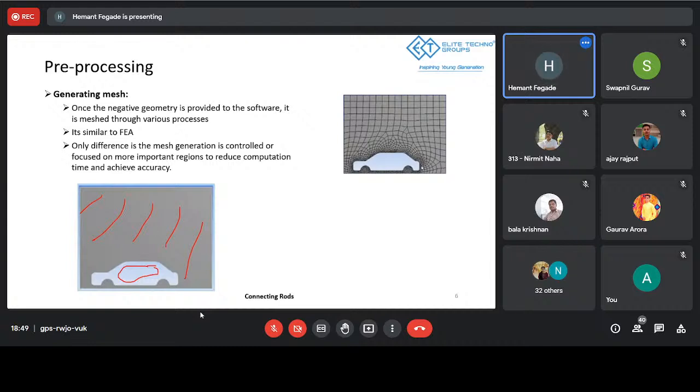And in meshing, basically what happens is we divide this geometry into small parts, as you can see over here. This we do because we need to calculate the property within a small particular cell. Because if you calculate the property over this big space, usually your properties have weird graphs, weird curves.